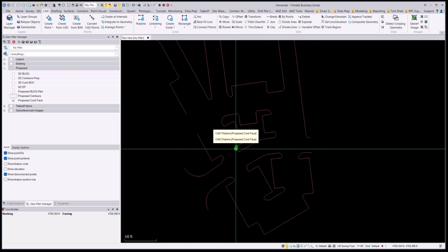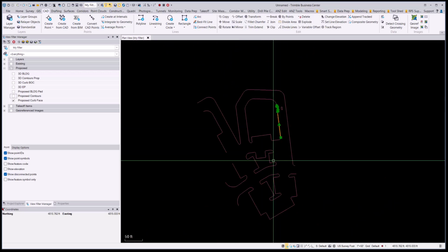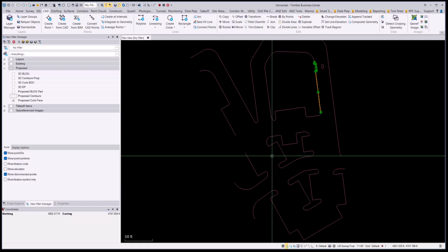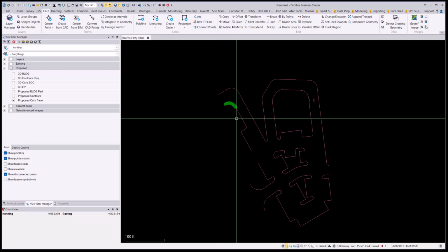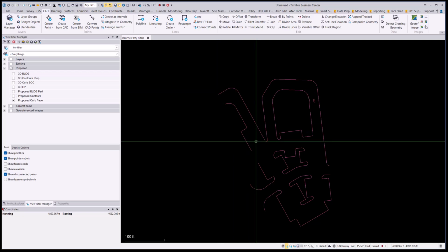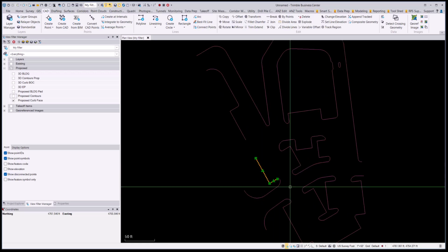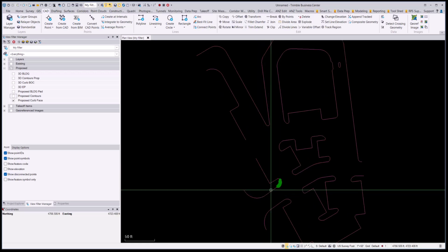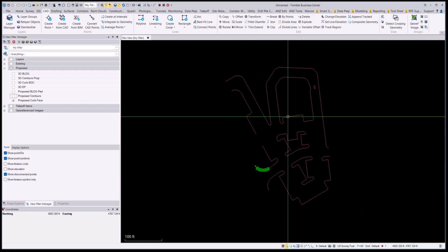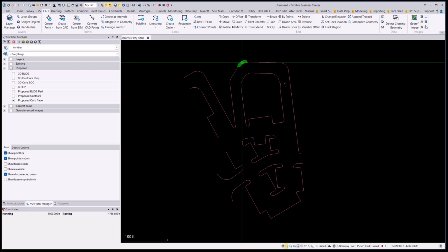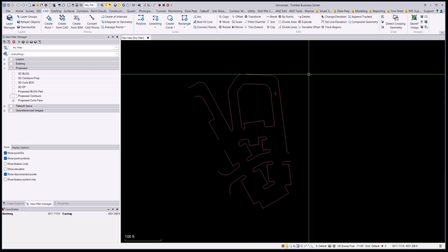So when we start doing our subgrade depths, I need all this to join and be closed entities so I can have a closed area or a potential closed area so that it drops my subgrade area down. Okay, and plus when we elevate based off spot grades, I don't want to have all these individual segments. I want it to be a nice long continuous run that I can elevate without hitting each one separately. All right, so we're going to try the join command on this one.